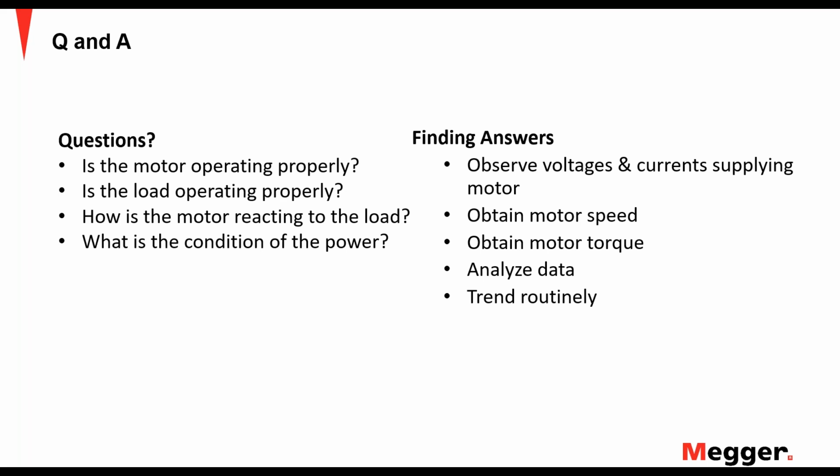And if my pump looked like my rock crusher, then I'd be upset. Then something's going on with that pump, more than likely cavitation. If my rock crusher looked like the smooth pump, then there's an issue with the rock crusher. Is it doing anything? Is it turned on? So what's proper for that load? What's proper for that motor?